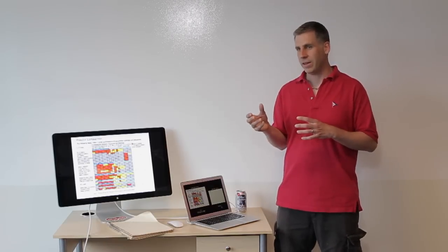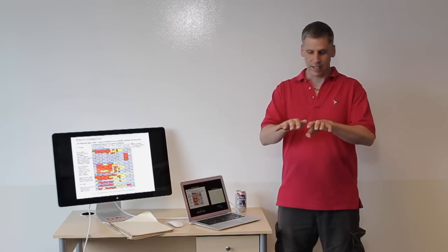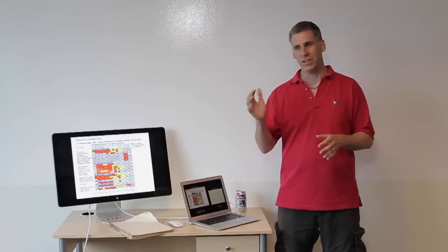Based on that, with injection molding, I can get 7,500 shots a week. And then I can do multiple cavities. Whereas right now, you need a lot of 3D printers to support that sort of volume. And it would also be more expensive when you consider the electricity. Second is if you use FDM, which is like a MakerBot, it does leave a little aesthetic bump on the surface, whereas with injection molding, you can do what's called mirror spark, which is just optically clear. And then also, 3D printing is not dimensionally stable, so it tends to have pretty significant part-to-part variation, whereas with injection molding pretty much every part's exactly the same.